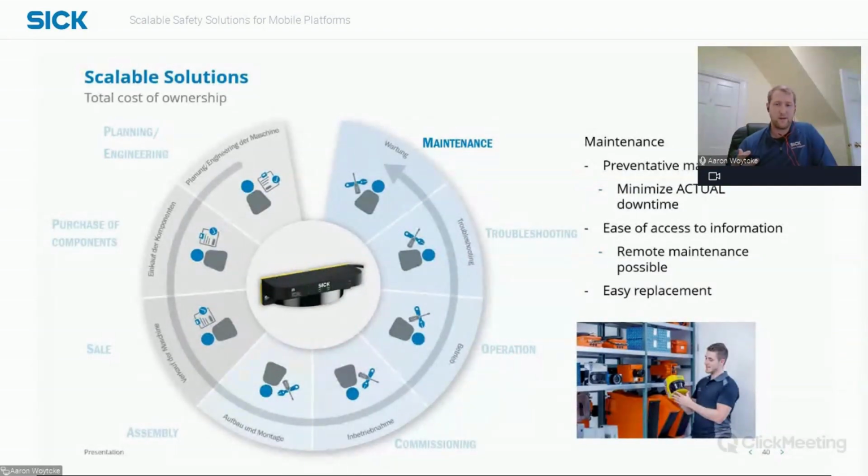So we can provide an error code or a warning signal to tell a maintenance person that a screen is dirty and needs to be cleaned, but the vehicle can still run. What happens is that this maintenance person schedules a time when the vehicle is docked next, when there's no productivity happening, it's just recharging the battery, and goes and wipes the front screen. So the result of this is that there's no efficiency loss and minimal labor costs needed to clear that warning.